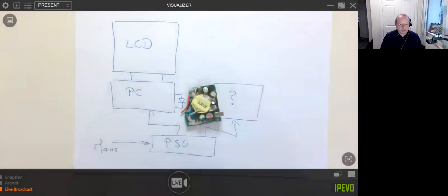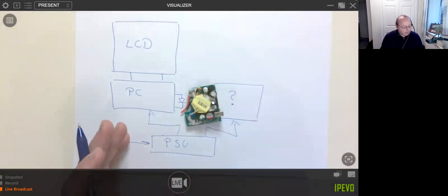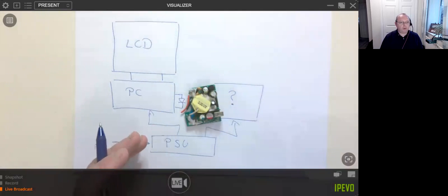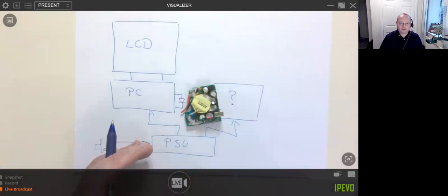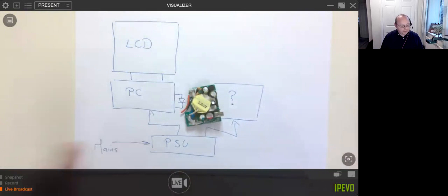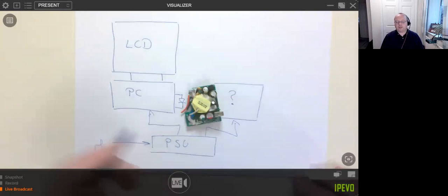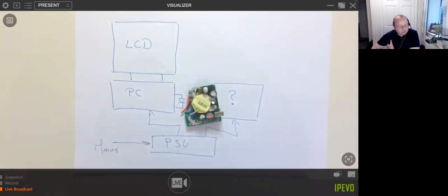So you want to have in the design of your arsenal, certainly under the current world climate where you can't buy anything, a number of components that you can just drop in and replace. But those drop-in replacements have to be built into the approvals file at the point of design. Thinking that, oh, great, we've run out of components, we'll just swap that processor for another one and life will be good. It so doesn't work like that, because if you think about it, changing a processor is a material change to a design.